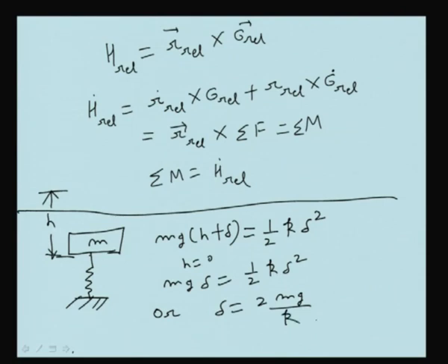In that case the deflection will be 2 times the static deflection. Static deflection is mg by k.